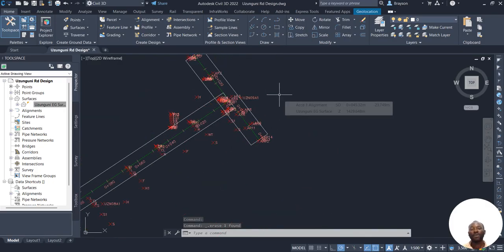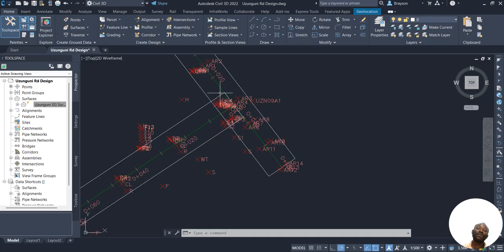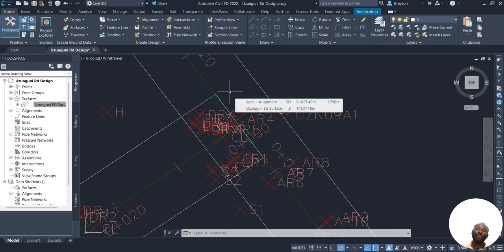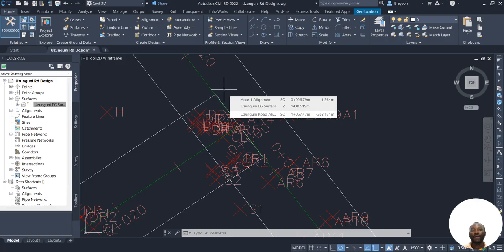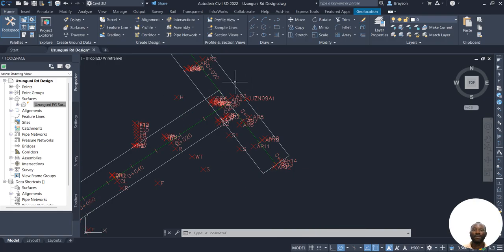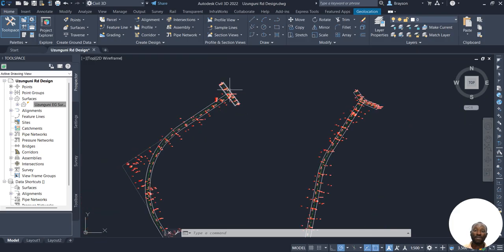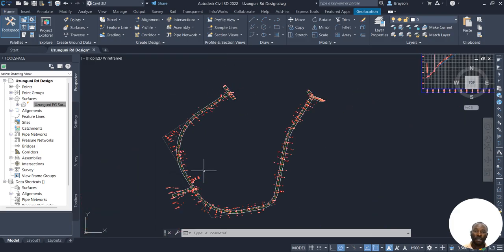You have to do something we call hydraulic drainage calculations or hydraulic studies. When you do the hydraulic studies, you get the catchment area. The catchment area will give you the discharge, right? And the discharge will decide the dimensions of the drainage system, right?